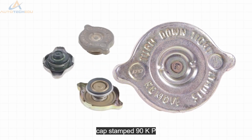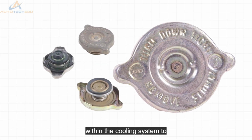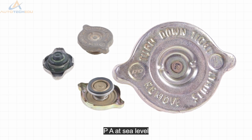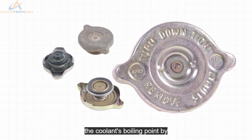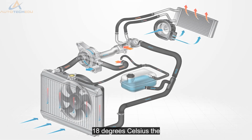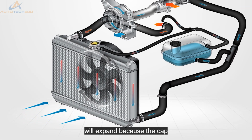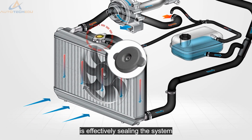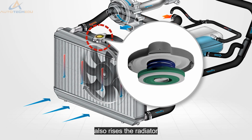A radiator cap stamped 90 kPa will raise the pressure within the cooling system to around 190 kPa at sea level, which will in effect increase the coolant's boiling point by 18 degrees Celsius. If the engine heats up and temperature increases, the coolant will expand. Because the cap is effectively sealing the system, the pressure also rises.